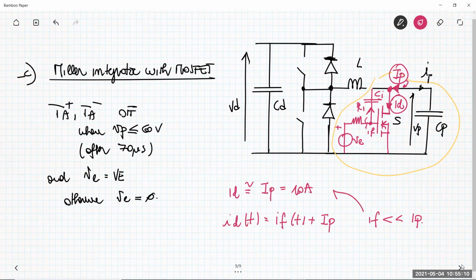Okay, so in order to get this approximation, when you operate these circuits in which you have this capacitor across the gate and the source, you are effectively exploiting the Miller effect. Okay, this discussion was already made to students in mechatronics during the section of lectures devoted to the devices.